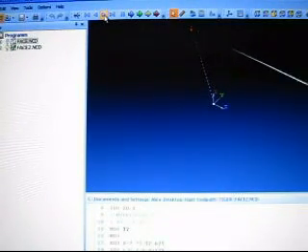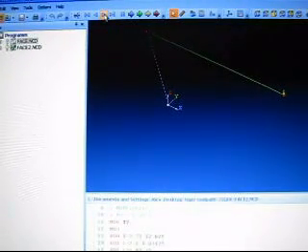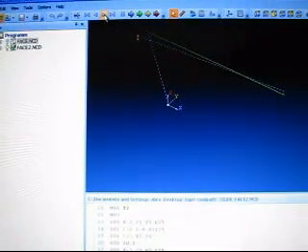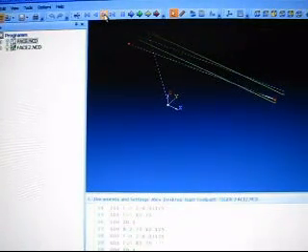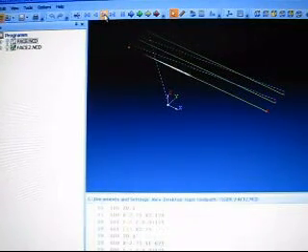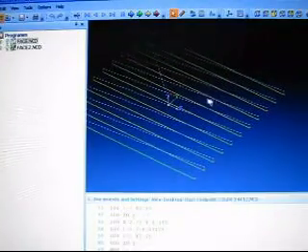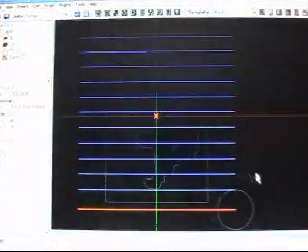All right, then it's going to proceed to cut with a climb mill style. Then it's going to jump up to my clearance, go back, wrap it back, jump down off the part, and do another cut. And it's going to jump up, back, wrap it back, down, and do another climb cut. It's climb milling right here, in this direction. It's just going to keep doing that and climb completely across the part, facing it off. That's a facing operation. That's how you program it in Mastercam. It's a really simple thing to do.